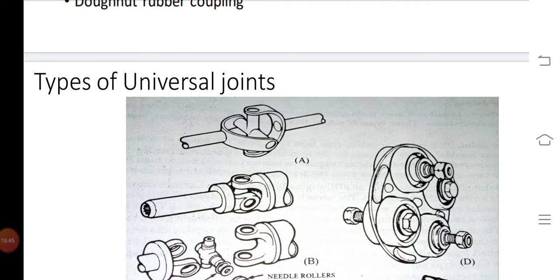Universal joints are incorporated in the vehicle's transmission system to perform in a better way, like propeller shaft end joints between the longitudinally front mounted gearbox and rear final drive axles, and rear axle drive shaft end joints between the sprung final drive and the unsprung rear wheel stub axles.